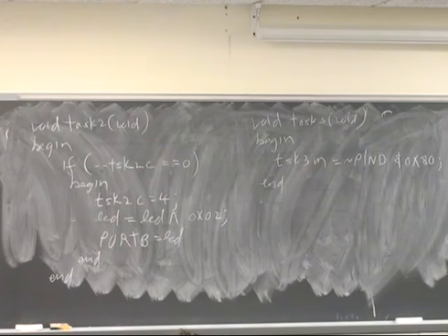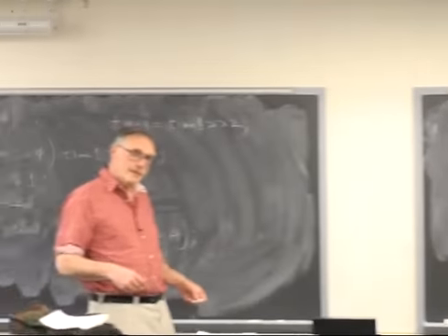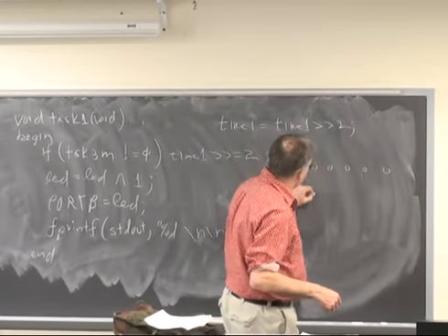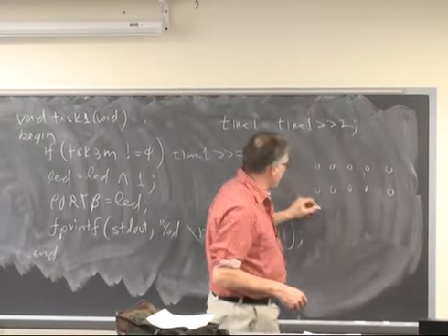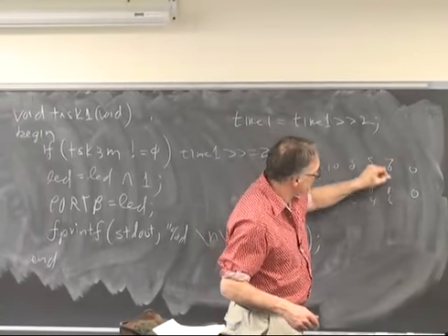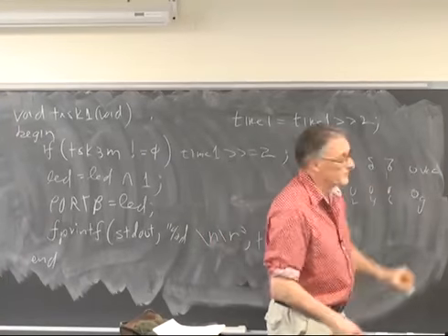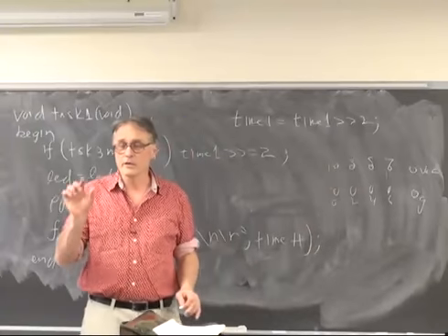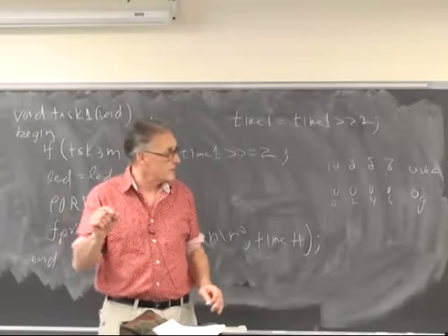On the STK500, as you may know from the photographs in the lab, each port is brought out onto a 10-pin connector, in which we have bits 0, 1, 2, 3, 4, 5, 6, 7, ground, VCC. So there's a 10-pin connector on the board that carries 8 signals plus ground and VCC.